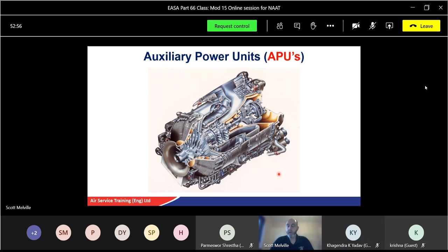It's a power unit. Electrical power, hydraulic power, up to a certain amount. Some APUs we can't do everything at once. We can maybe use one hydraulic system and then switch over to another one. We can use it for everything, but very slowly. So we can use it for checking controls on certain aircraft, as long as you operate them slowly. But certainly electrical power. So every time you go on a big aircraft, on a holiday or wherever, flying to another country, you'll hear the APU running.